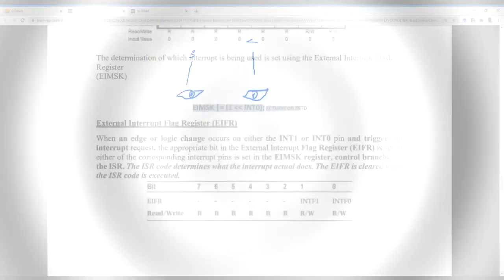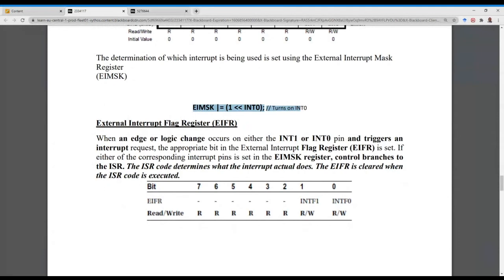At the beginning, these registers are masked. So basically, we are not using those switches, those pins, as interrupts. If I want to use pin 3 as an interrupt, I've got this connected to pin 3, so I unmask it. If I want to use both pin 3 and pin 2 as interrupts, because I have two switches that I want to be responded to, then I unmask both, which means they are in use.